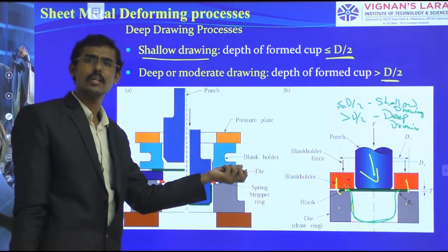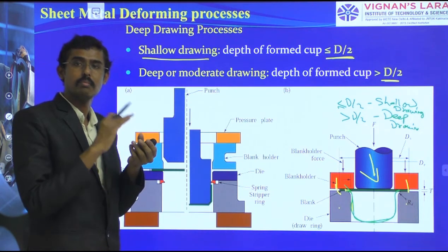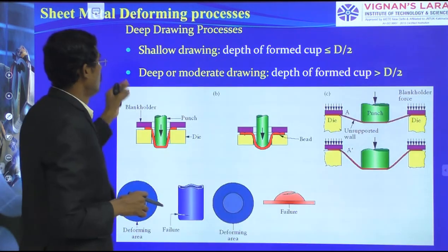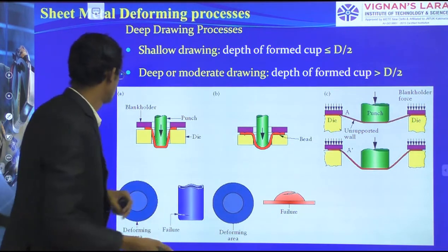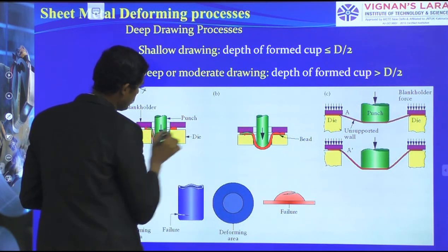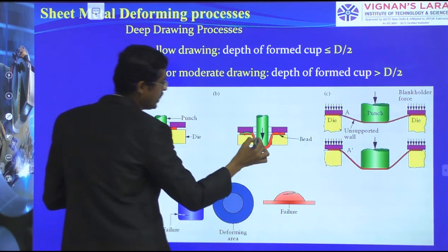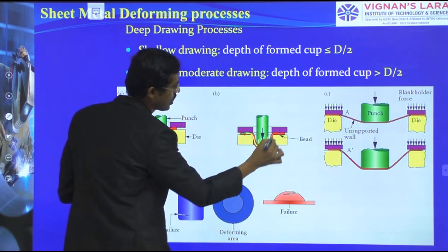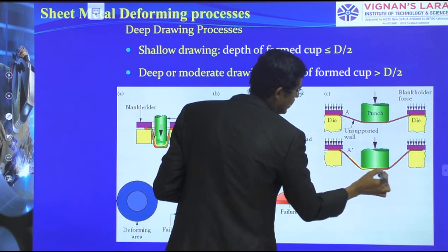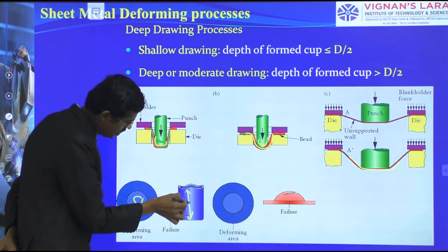It is also one of the sheet metal forming processes, along with shearing, blanking, punching, bending. So deep drawing is also one of the squeezing methods. We have some other methods too. A cup is formed, see here like this. Here the die is flat, therefore I am getting the product flat. The die is round here, therefore I am getting the product round. So it is open punching, with free ends. It is lengthy, stretched out, deeper. So this is how this forms.